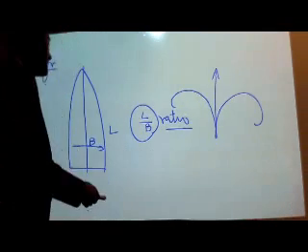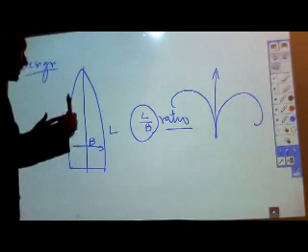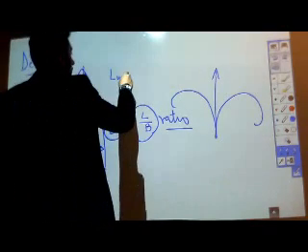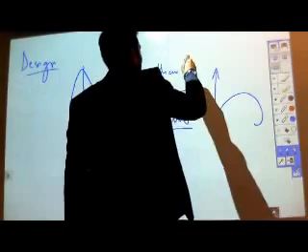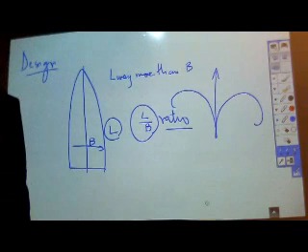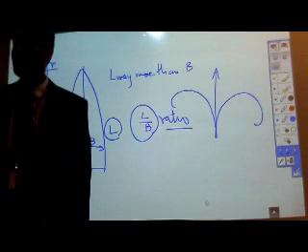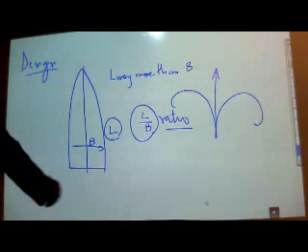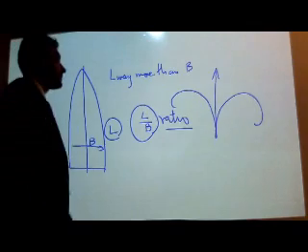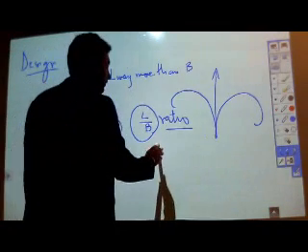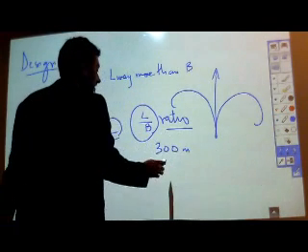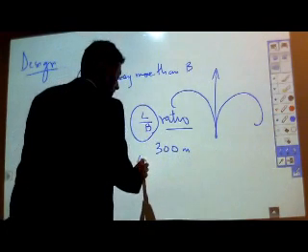For a directionally stable vessel, generally the profile, the underwater volume or the design of the ship, the length will be way more. The length to breadth ratio is going to be higher. For example, container vessels. They are way longer than they are fat. They have a very small beam by comparison. So length over breadth. Generally, a container vessel of, let's say, 300 meters long, versus a beam of about 40 meters.